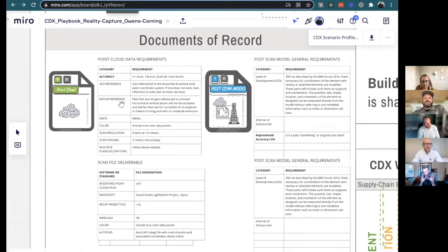To understand the thickness between mortar joints and all of that, if it's a highly detailed model, you're going to want to scan it at a certain resolution and probably scan in color. If you're trying to contextualize the building itself, you're probably better off just using a UAV and tie it to control.